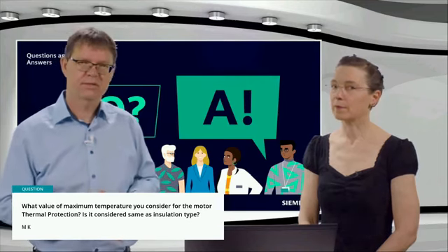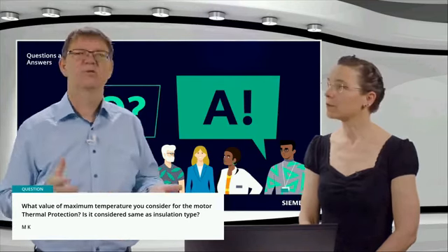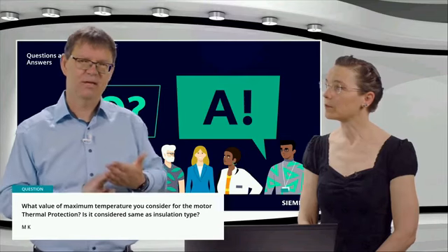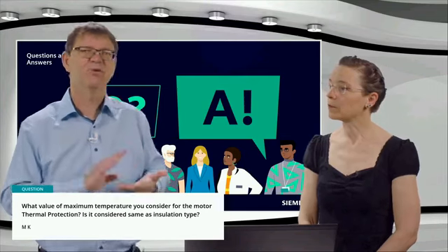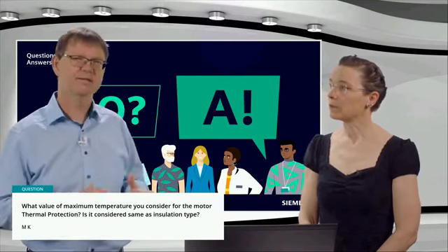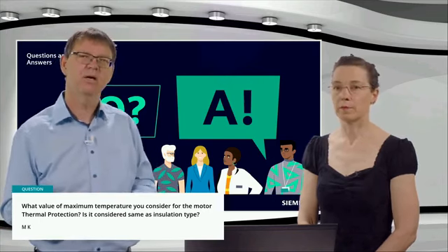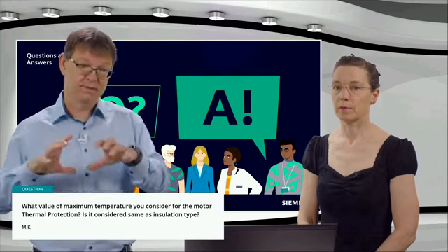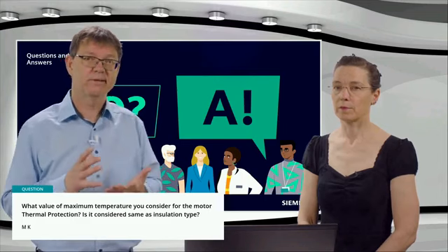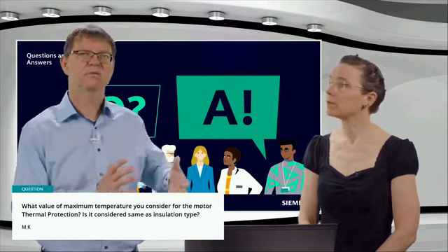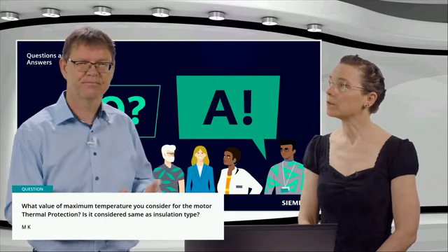Here we don't consider that at all, because we consider just the data we have from the motor manufacturers: the number of starts, the starting time and the starting current all together. With that, we build up our model for the rotor. And again, this rotor temperature model is completely independent of the stator temperature model.